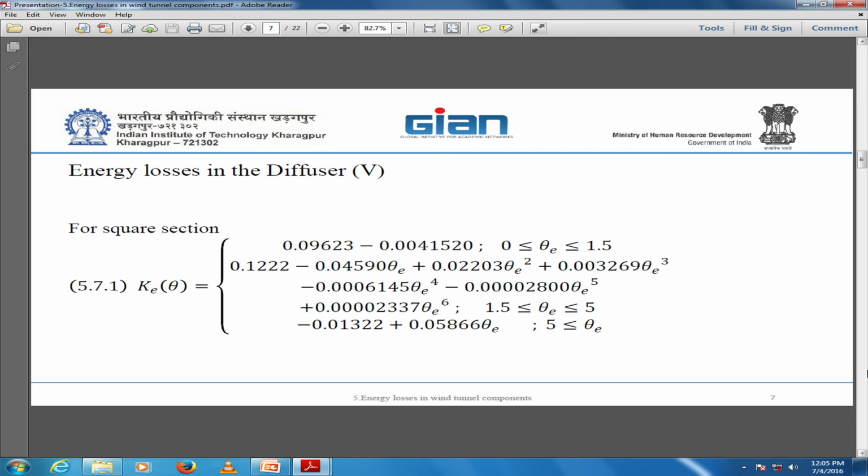I gave the whole formula for you. The other 4 boundary conditions, what are they? First and second derivatives on both in and out. You want the section to be parallel, both entering and the exit, and out of that you get this nice formula.